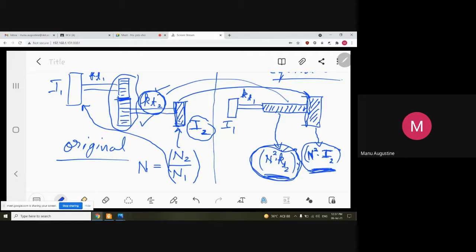So only this factor of n square has to be remembered. All you have to do is multiply all the driven side parameters with n square, where n is the speed ratio, so you get the equivalent replacement entities. And once these have been put in place, you can conveniently ignore the gearing mechanism.